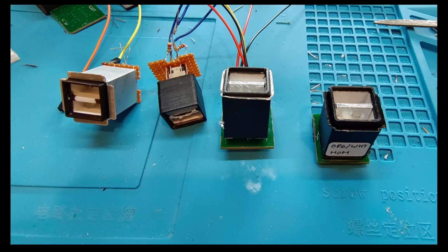The construction is this: this is the case of the LED, and below that there's a micro switch that I'm using, and the LED pins are pushed through to the PCB and soldered there, kind of acting as a guiding rail for this housing to move up and down based on the tips of the switch.